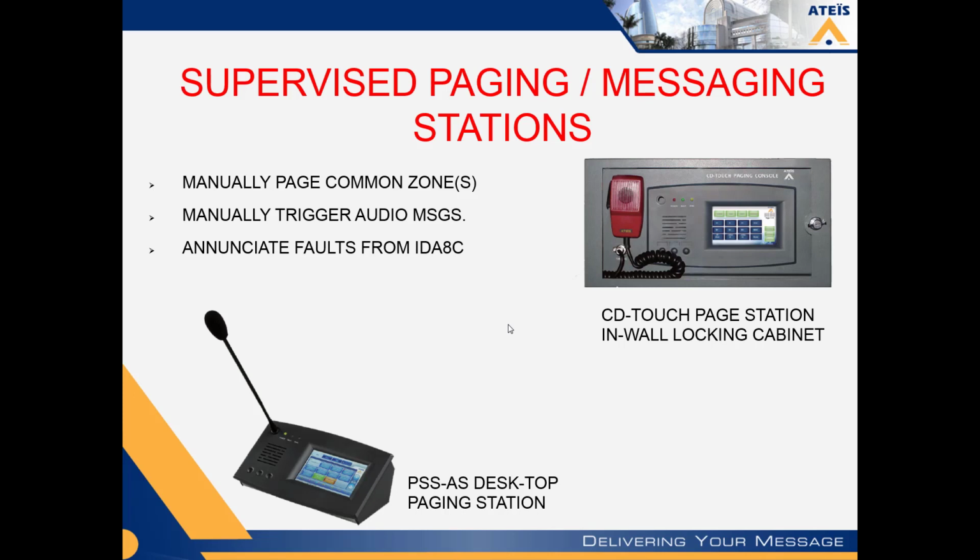If the ID8C is located in the admin area, and if it ever has a fault and it beeps, just like a fire alarm or security panel would, and somebody's going to hear it, then you might not need it at the stations. But if the ID8 system is in an electrical room or a data room somewhere, and nobody's there all the time, then you definitely would need the fault messages enunciated at a manned location where a paging station would be. And it has touchscreen operation, and you can put as many of these on the system as you want. There's plenty of ports on the system to handle what I think any normal school or educational facility would require.